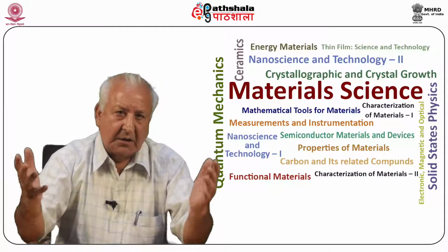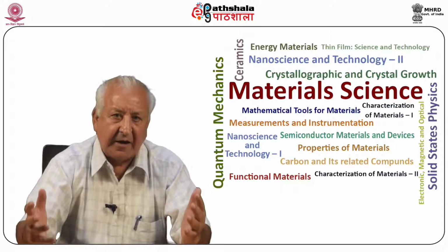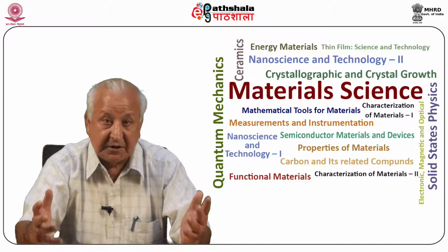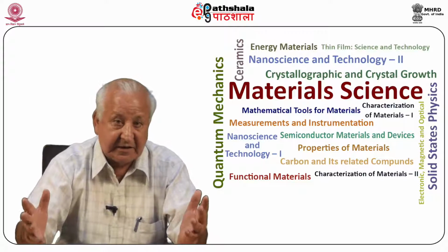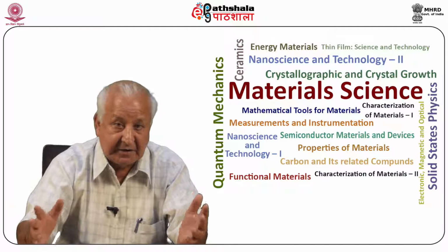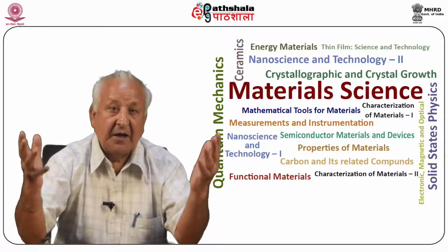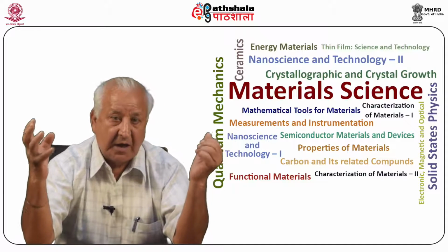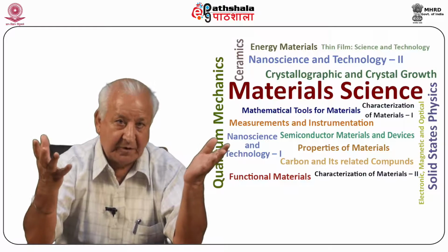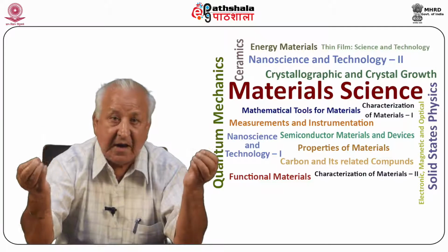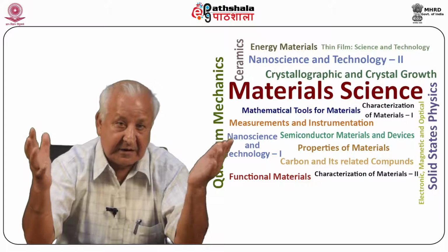Bridgman-Stockbarger growth. The techniques were originated by Bridgman in 1925 and Stockbarger in 1938, and so are named after them. In these techniques, a crucible containing the material to be grown is lowered through a furnace in such a way that the lowest point in the crucible cools first and the solidification surface rises slowly up the crucible. It means that the melt contained in the crucible is progressively frozen to yield a single crystal.